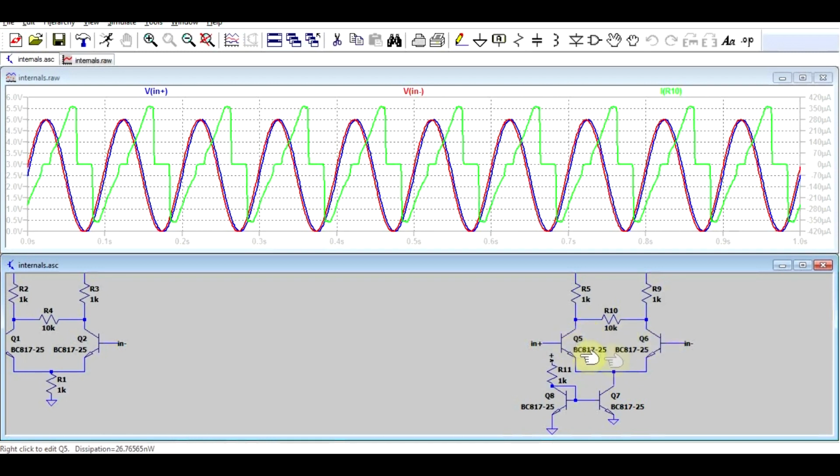Now if we look at the transistors in the comparator itself, we know that between the base and emitter we have the PN junction. So if we actually want to drive any of these two transistors, we need to have the base voltage higher than the emitter voltage by around 0.5, 0.6 volts, which is added on top of the voltage drop on our lower transistor. So in total, if we actually want to compare two voltages, we need to drive the two transistors and the one on the bottom, so the minimum voltage between our inputs and the ground needs to be around 0.7 volts. You cannot use this sort of input stage with input voltages lower than 0.7 because of this.